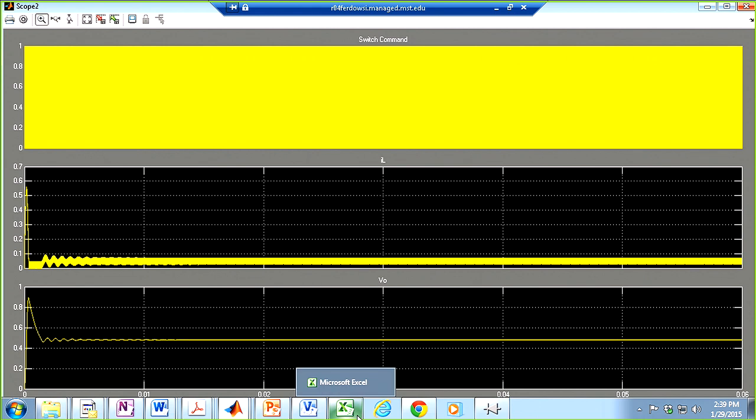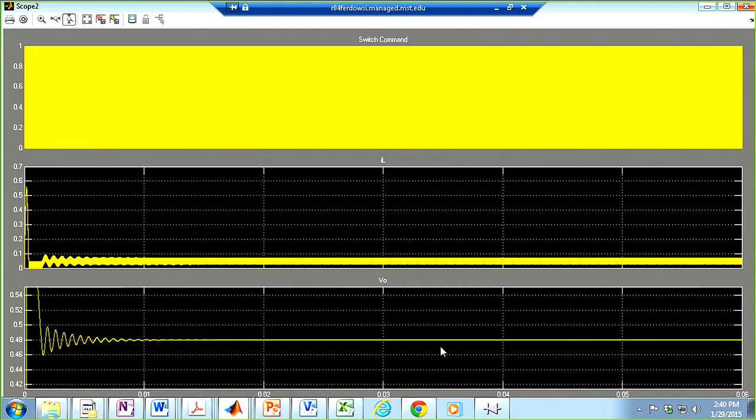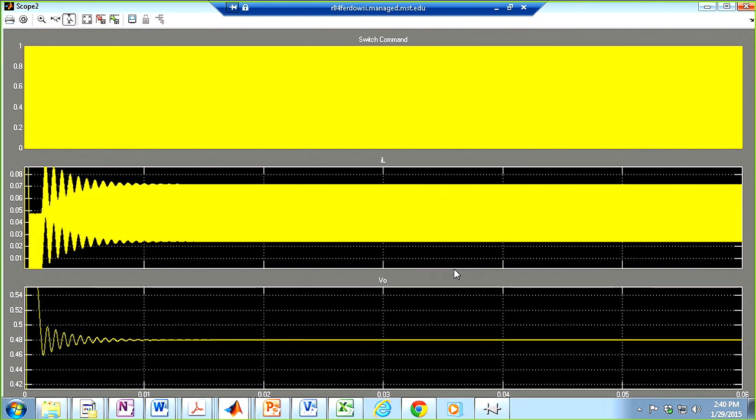And surprisingly, you do, actually. Well, this is simulation, or the design is so good, but usually when you go to very small, excessive amounts of D, the system is going to mess up. But yeah, the output voltage is 480 millivolts, and surprisingly, you are still in continuous conduction mode.